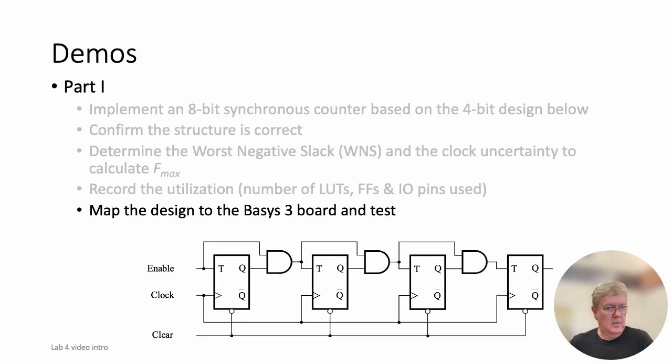Once you've completed the design and analysed it, you can then implement this counter by embedding it in another top-level design that connects the various components, the enable pin, the clear signal, and the clock to various inputs that are provided by the board, so that we can also see the contents of the counter.